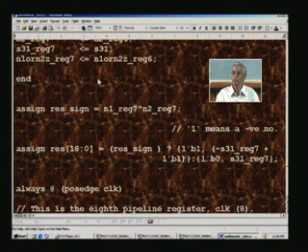Similarly, if you exclusive OR 1 and 1, it will be 1 0, you have to drop the carry 1, so what you get as the result is only 0. So in this case also minus into minus is plus, and similarly plus into minus, if you exclusive OR 1 with 0, will give you 1. So 1 is the final result which will be put here, and that naturally is a minus sign because 1 stands for the sign, 0 stands for the positive number. It is a mere exclusive OR of the sign bits of the 2 numbers N1 and N2 which we started multiplying. 1 means a negative number.